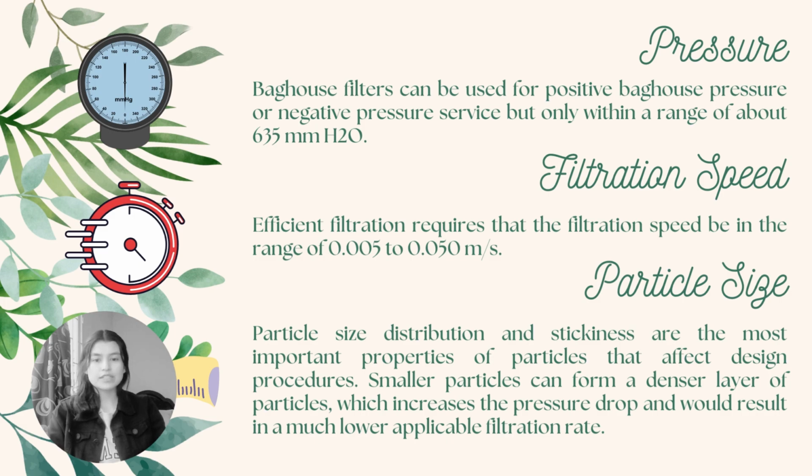And particle size. Particle size distribution and stickiness are the most important properties of particles that affect design. Smaller particles can form a denser layer of particles, which increases the pressure drop and would result in a much lower applicable filtration rate.